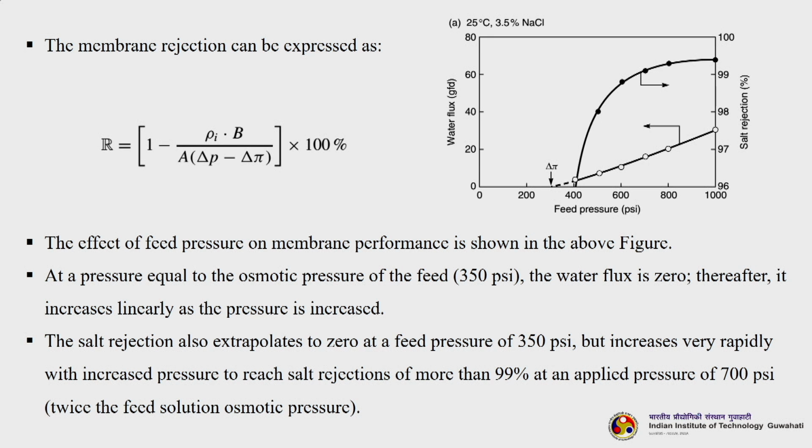You can see that at a pressure equal to the osmotic pressure of the feed, that is 350 psi somewhere here, the water flux equals 0. Thereafter it increases linearly, you can see this is your water flux. As we increase the pressure, the water flux increases linearly.